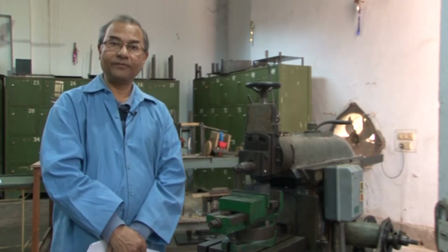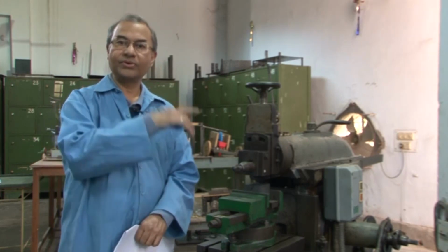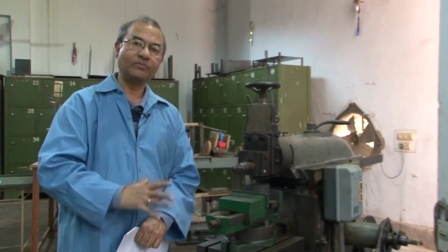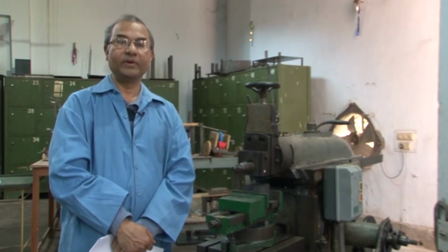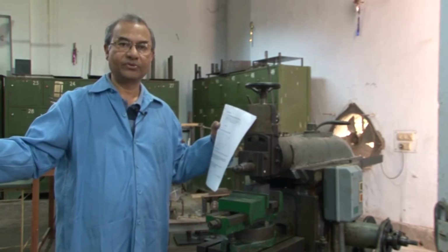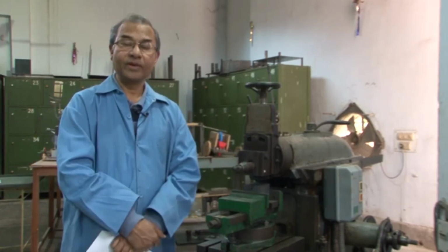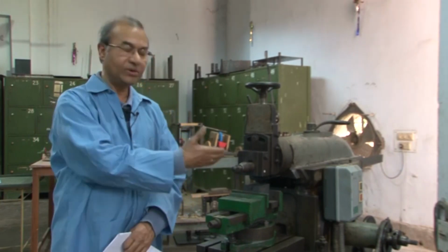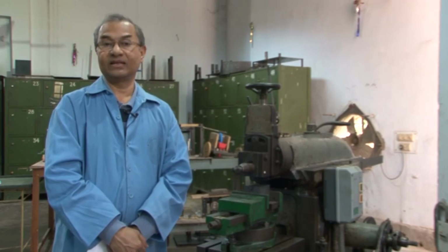While in planing, if you make the same kind of Whitworth quick return mechanism, the bull gear, which rotates continuously and gives the movement of the quick return mechanism, becomes very big. Therefore, if you make the same mechanism for planing, where you have very big surfaces to be machined, the machine would have been very big. So, the quick return mechanism in planing is different from the Whitworth mechanism used in shaping, and in planing the loose pulleys and cross belt system is normally used.